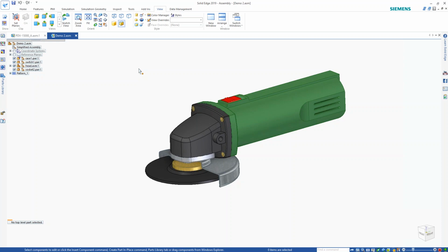If you're simplifying a component inside your assembly, then it's going to process the as designed component. And if you want to make sure that it's doing that, I haven't done this in a few years, and I haven't tried it with this auto simplify, but as far as I remember, you would just come up to your top level assembly and say use design components before utilizing that. But if you did do that outside and you brought just that simplified model in, then the density is not going to be correct for that component.